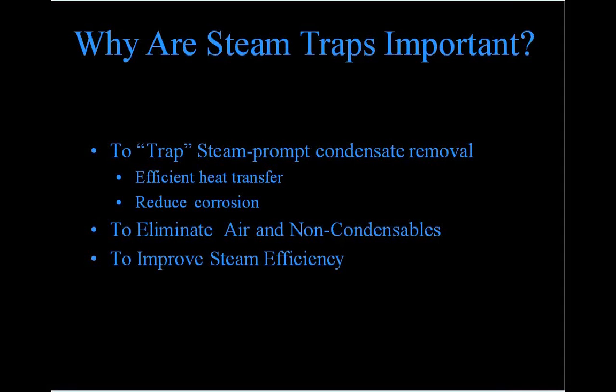And then, speaking of efficiency, just to improve your overall steam efficiency, again, we want to get the water out as quickly as possible. I like to use the example of a cooker, and if you were making soup in a vessel, a blanketed vessel, you'll have steam on the outside, and that's going to heat up the soup that's inside of the vessel. Well, if you have water in the bottom of that, or you have air in the top of that, you're not getting that steam up against the wall as much as you want, so you don't have the efficiencies that you're looking for.